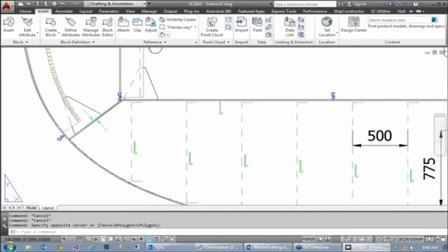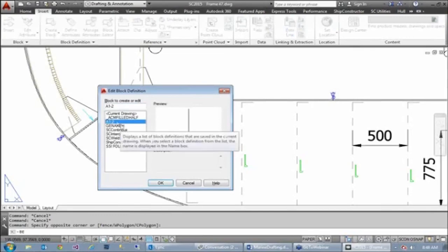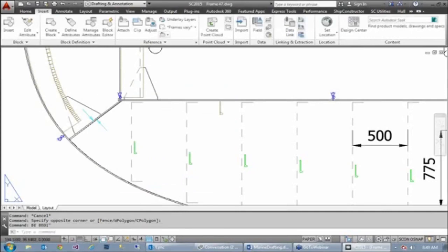So if I look at the block list, I'm not sure if this one has any specifically, A12. This is an end cut name in my end cut catalog. I can edit this block and change the definition of what it looks like. If it's a snipe, then I can say draw a line at an angle, and it will show a snipe end cut, and that information can come through. So you define the blocks in the template for every one of your end cuts, and it will use whatever the end cut definition is for each one of the stiffeners. So yes, you can replace those.